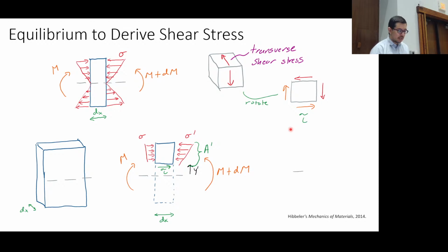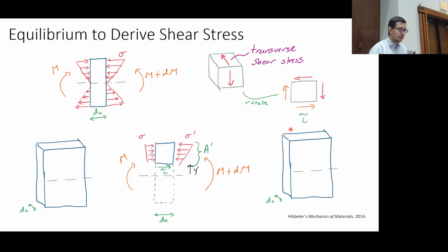All right, let's keep going. What we have is this shear stress and these bending stresses acting on a selected area, and this area is going to be this one. We have some width, acting a distance y prime.